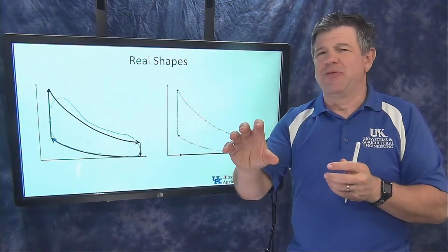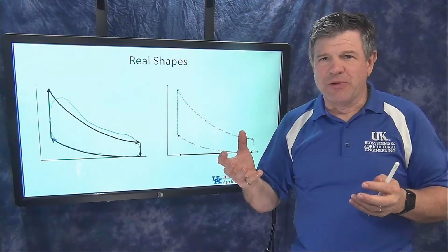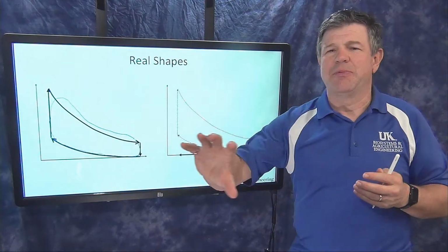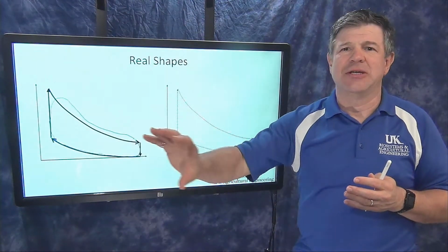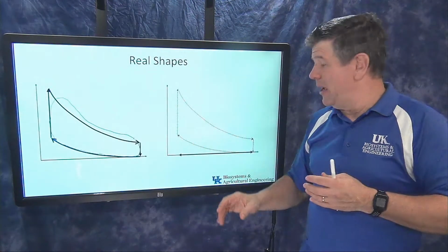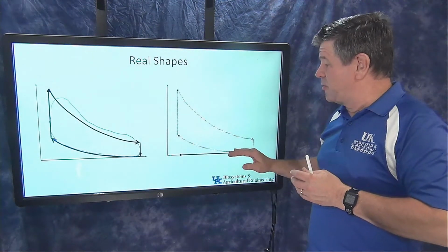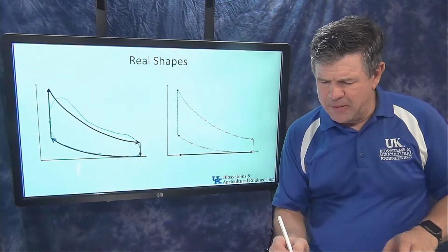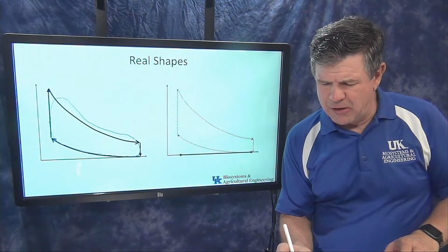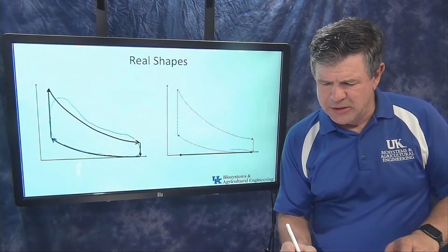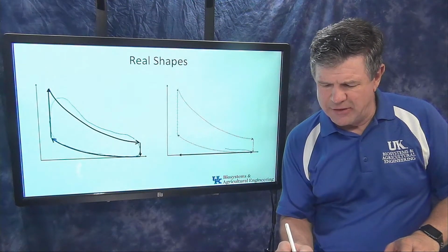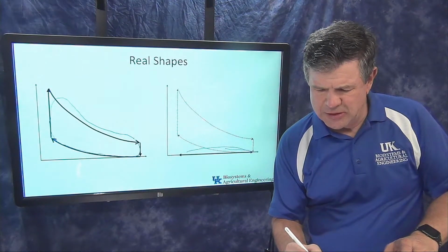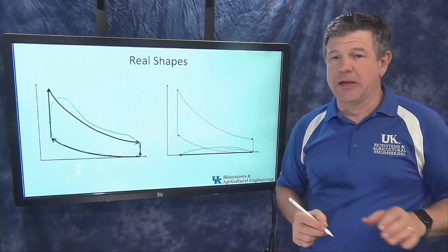And then it has to go out through the pipes, and if I've got mufflers and catalytic converters and whatever else on the exhaust, I have to push that gas through that exhaust to get it out through the engine. So, oh man, yeah, there's going to be some resistance pressure here. So instead of just going straight along that horizontal line, what I'm actually going to get is a curve that loops up like this. I'll exaggerate this a little bit and make it kind of high, and it's going to look something like that. It's going to loop up around like that.